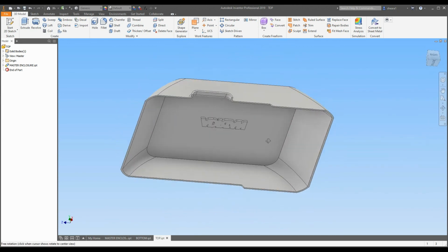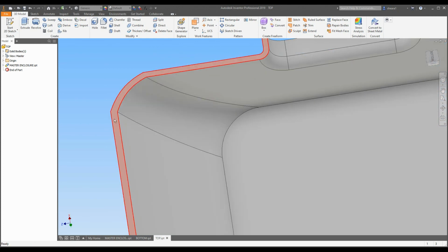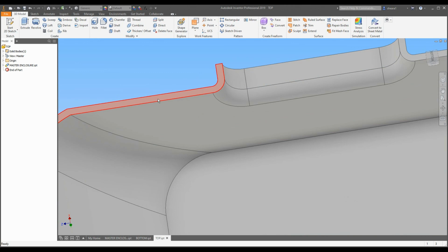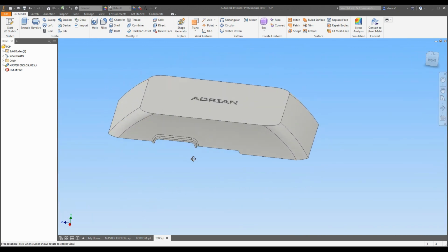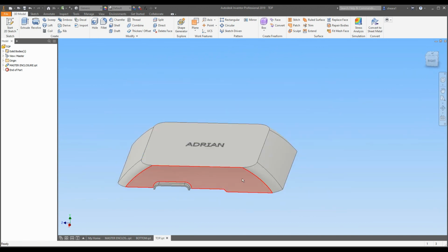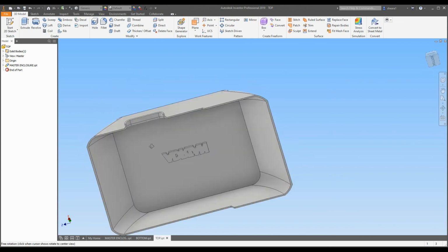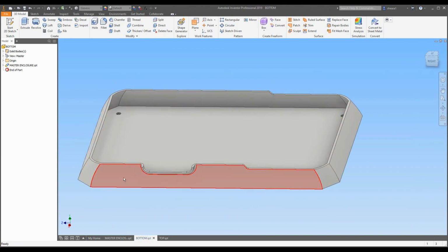And basically at the end, you can always model some grooves in these if you want them to fit together like a nice cohesive one piece, or you could always glue them together or something else. But basically that's how you design for manufacturing. I would put both of these parts onto a 3D printer tray, and they would print from the bottom up like this, and from the bottom up like this. I can actually show you that in just a few minutes.